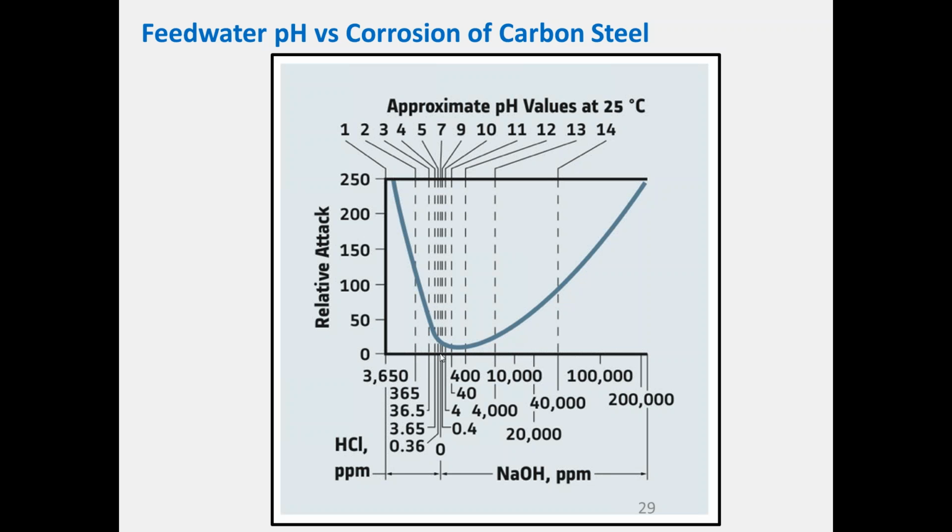So in most boilers and power plants, we're trying to get a pH that's alkaline, normally 8, 9, 10 in the feed water, and same for the boiler because that's optimum for the materials. Now, whether you can obtain that pH depends on your plant design and what your steam is being used for, or whether there's hot water being extracted from the boiler for another process. It may impact on other materials in there.